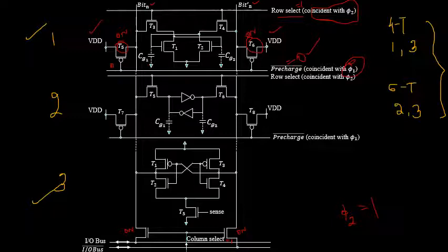I told you that for the 4 transistor type of dynamic memory cell, you are supposed to draw the first circuit as well as the third circuit. So it will have a continued connection wherein the signals stored in bit n as well as bit n complement lines will get discharged through this transistor which is turned on, in terms of the input output bus as well as the input output bus complement.